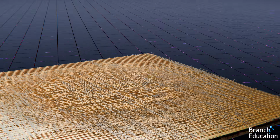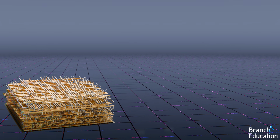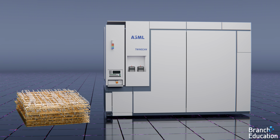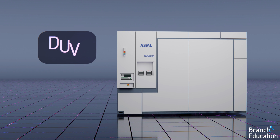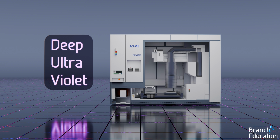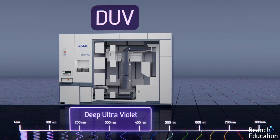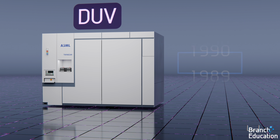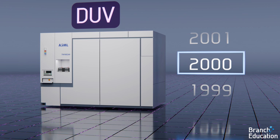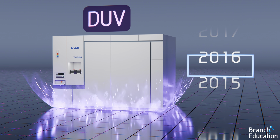However, the upper wires are substantially larger and are patterned using an entirely different machine called a DUV, or Deep Ultraviolet Photolithography System, which is also built by ASML and uses a deep ultraviolet wavelength of light. DUV lithography tools were introduced in the 2000s and are still incredibly advanced machines.